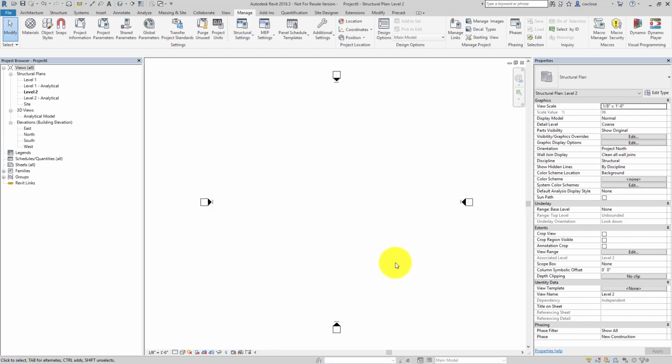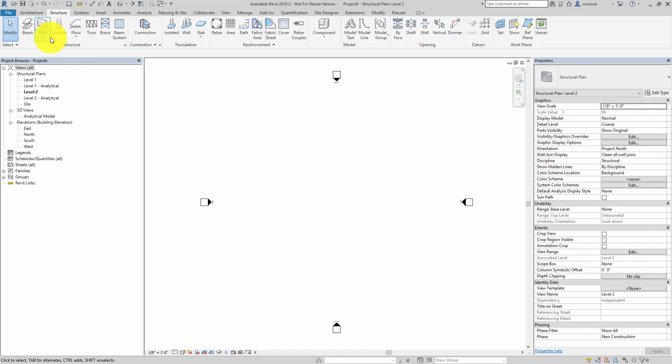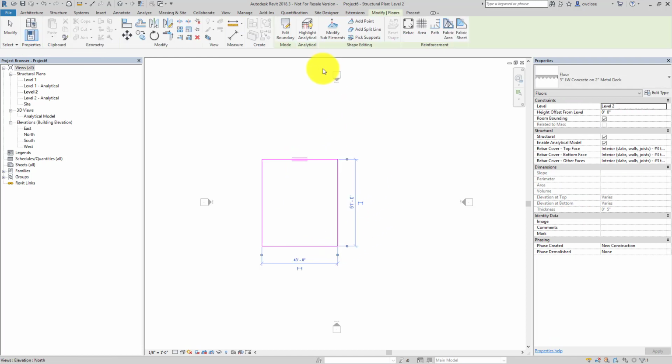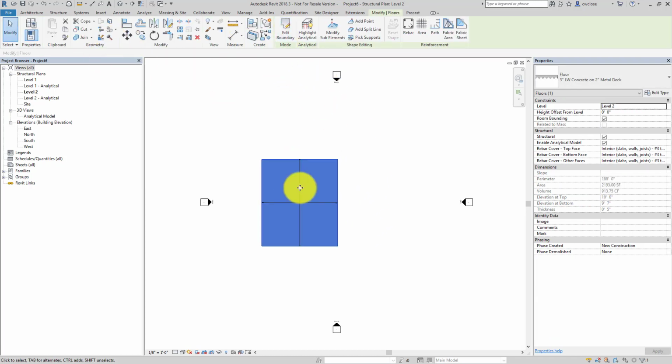So there are two approaches that I like to use. It just kind of depends on the project. If you're not doing a workshared project, I think the easiest way is just doing a project parameter. So what you'll do here, let's just quickly create a couple of structural floors. We're going to keep this just simple. Obviously, you can apply this across different categories.